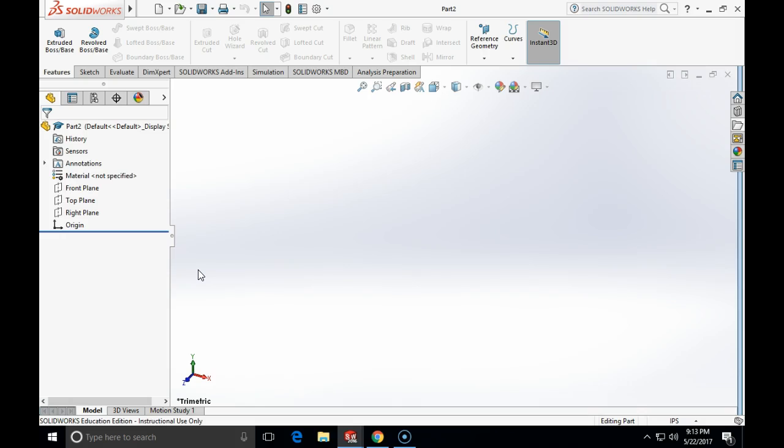However, if you use the Hole Wizard, the subsequent STEP file that you may save for your CAM system will be annotated in a way that CAM knows it is a hole, and in the automatic toolpath generation will use the proper commands. So that's very important, although on the model on the screen it is not always displayed.